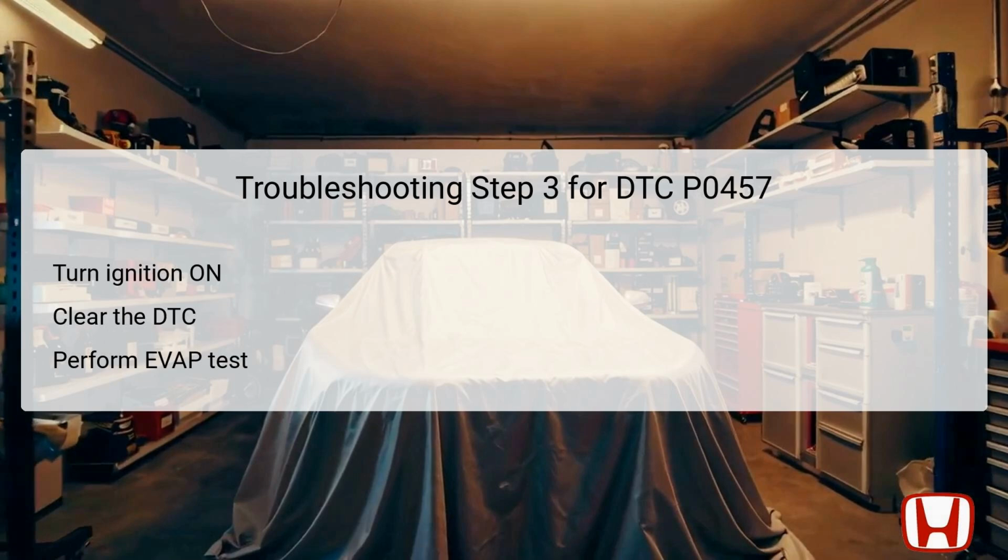With Step 3 in the troubleshooting process, the emphasis shifts to confirming the initial diagnosis using the Honda Diagnostic System, HDS. Begin by turning the ignition switch to the on position or pressing the engine start button, which will activate the diagnostics. At this stage, it is vital to clear the previously recorded DTC using the HDS.